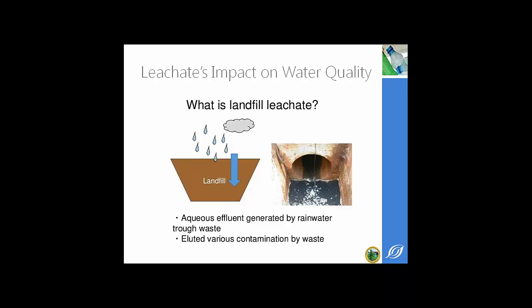Older landfills, especially those built near waterways, were tremendously affected by the leachate that would start to leak. And what leaks out of a landfill can definitely vary on the age of the landfill, the type of landfill, and the material. So if you have an older landfill that at one point was taking a lot of toxic materials, especially those with chemicals and heavy metals, and then the liquid is mixing with that, you have all of that going into the water system below, which is why it's such a huge contaminant and why it's so important.